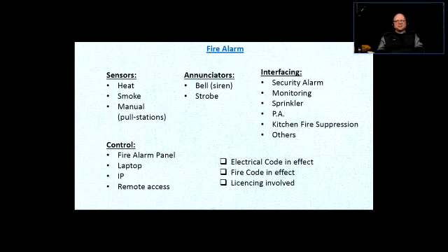So whoever is monitoring the facility would be notified, and they would be required to go into the sprinkler room and look at the sprinkler system and the pressure gauges and so on. If they see that the city pressure has gone down, and based on that, the sprinkler system pressure has also gone down, then it could be considered a false alarm.